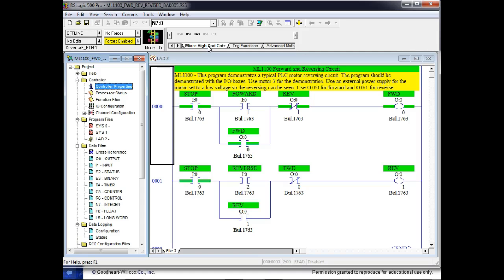So I can go back and scan it every once in a while, that's fine, but the counter won't miss any counts, right? You understand? If I'm looking at RPM, I might go out and read it every second, right? But that encoder's flying by in microseconds, right? So all we've got to do with high-speed counters is there's no high-speed counter instruction, right?